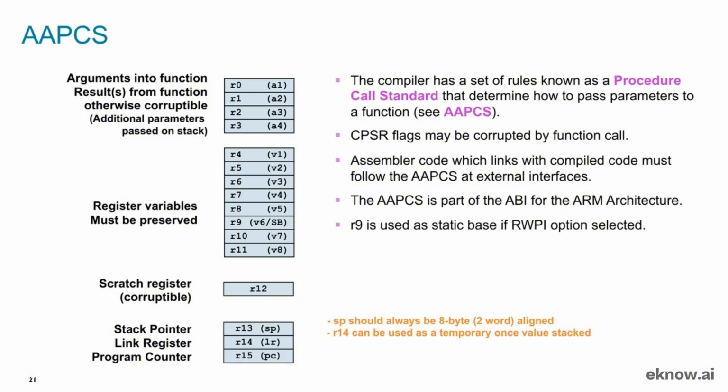Ultimately, if you're ever writing assembly code that needs to interface with C code, you must obey these AAPCS rules. This standard is what makes modular programming and software libraries possible on the ARM platform.